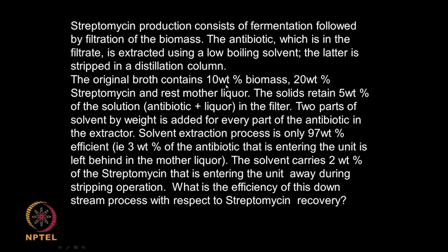The original broth contains 10 weight% of biomass and 20 weight% of streptomycin, and the rest is mother liquor. That means, suppose we take 100 grams, then 10 grams will be your biomass, 20 grams will be streptomycin, and the remaining 70 grams will be liquid. Now, when you do a filtration, the solids will retain 5% of the solution, remember that. So, solids are always wet, in a filter we cannot completely dry.